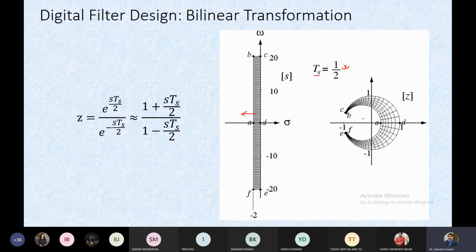So what we learned so far is the way of filter design for the FIR structure and for the IIR structure. For the FIR structure we start with the desired frequency response and use a window method, but that is not the only method. There are a number of other methods, so for details you can go through the book, but we chose the window method because it is widely used and gives quite an easy notion for designing. And then for the IIR system, we basically use analog filter design.